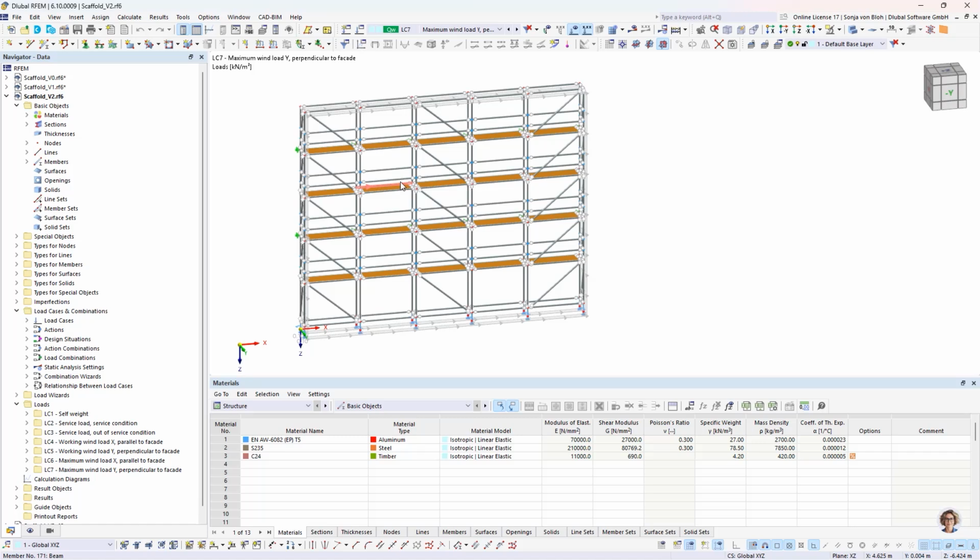In this webinar, I will concentrate on the ultimate limit state design of the standard. According to Eurocode 9, a second-order analysis considering the relevant imperfection is permitted. In this case, only cross-section checks are required, since stability effects are already captured by the analysis. The connections between the standards have been modeled as rigid joints. However, to account for the rotational play resulting from the slip in the plug connection, EN 12811 Part 1 requires the consideration of frame imperfections by angular deviations at the joints between vertical components. In addition, the maximum permissible vertical deviation of the base jack must be taken into account in the calculation.